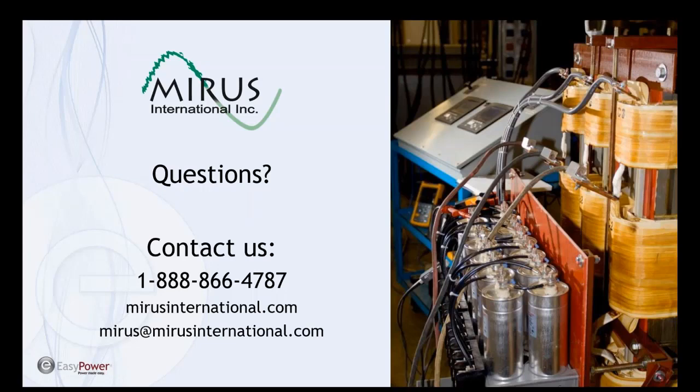Active front-end drives, which are defined as low harmonic, and although I have another presentation that discusses active versus passive harmonic mitigation techniques, have much higher losses. So they also introduce heavier losses and are much less efficient than the other solution.